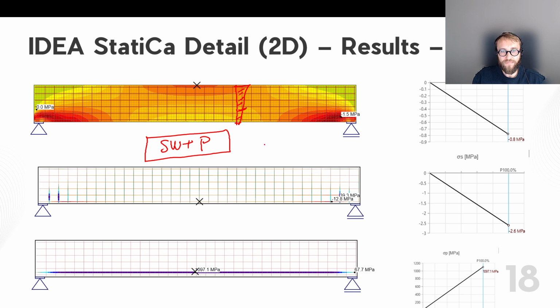So this is the level of the stress in the detail. The stress that is outlined here is called sigma 2, and this is the minimal principal stress under compression that is composed from the tensors sigma x, sigma z, and tau xz.